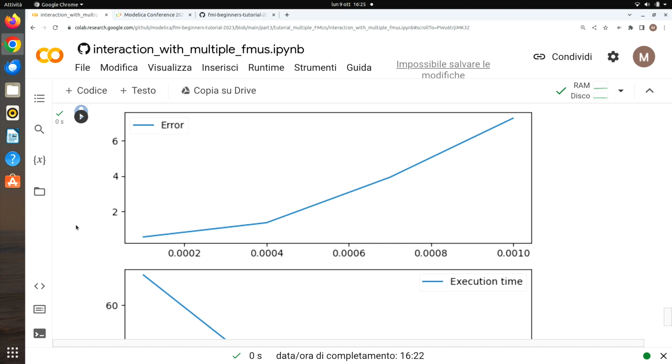Yeah. In general, you can also do it the other way around. You start with, let's say, a guess, and then you, for example, halve this communication step and see if something changes. If it's not changing, it should be converged. Yeah, exactly. That's the rule of thumb.